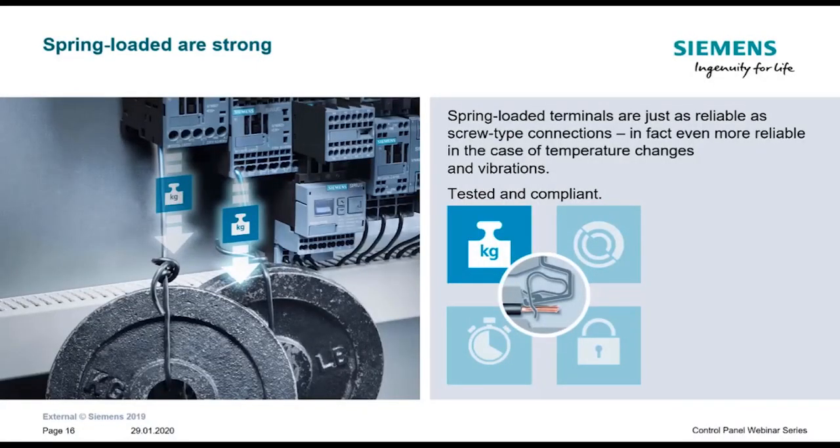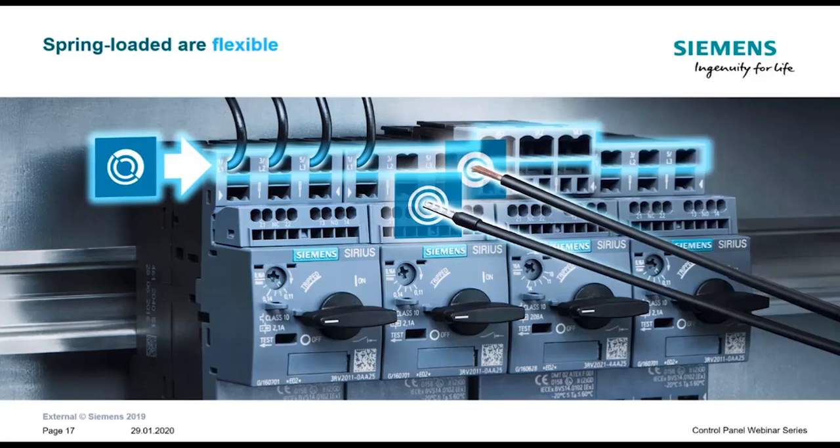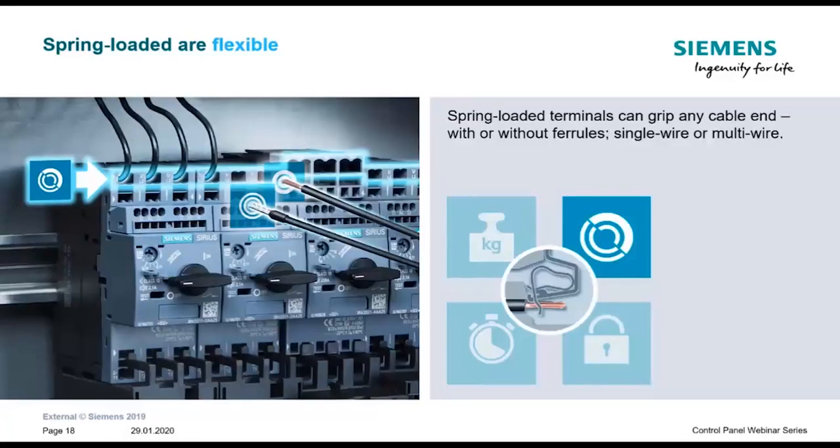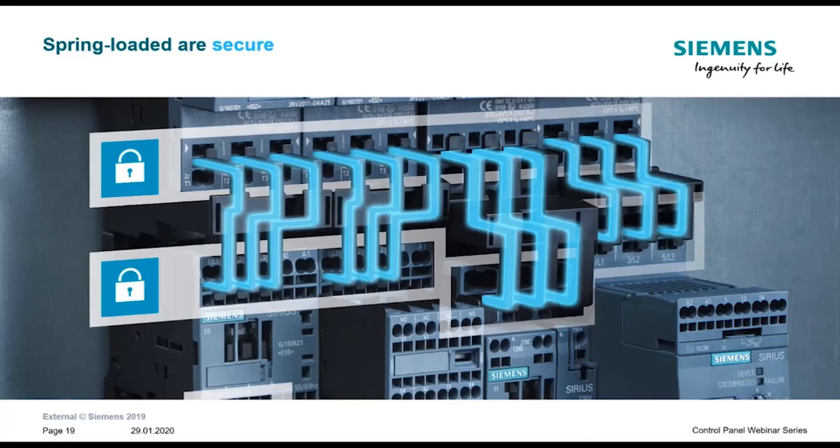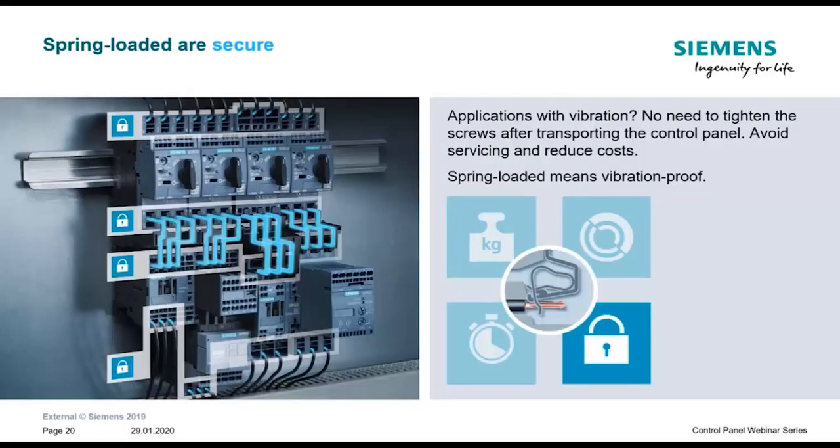Let me show you more about the spring-loaded terminals right now. The spring-loaded terminals are strong. These terminals are just as reliable as the screw-type connections. In fact, they are more reliable in case of temperature changes and vibrations. This has been tested in accordance with directives and standards. The spring-loaded connections are flexible because you can have them with or without ferrules, single wire, multi-wire, rapidly and easily. Spring-loaded connections are secure and safe.